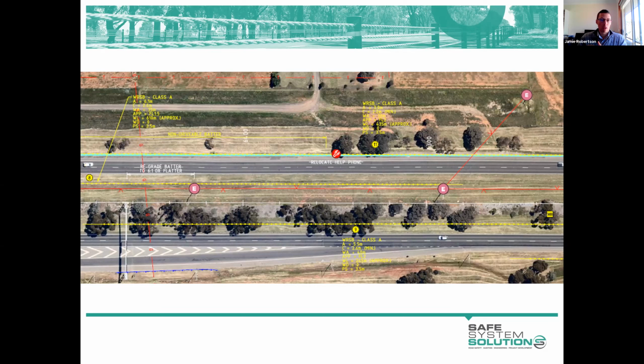We minimised the likelihood of nuisance impacts as well, but we did open up the possibility of a few things: rollover before vehicles strike those barriers, impacts at some high angles, and also it resulted in some hazards that were outside the clear zone that was adopted not being shielded at all.